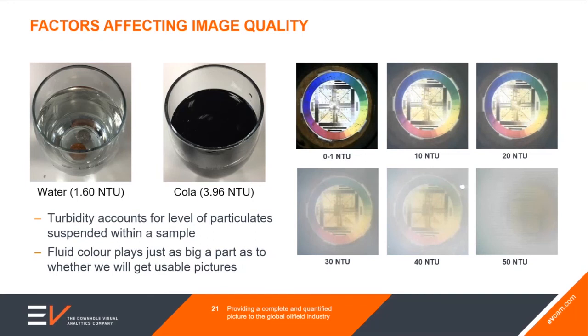We have very experienced operational engineers and a planning team who will go through different scenarios and mitigations that we can either circulate with a clean fluid, we could bullhead a static column to get it to the right depths and area of interest, or we can actually produce the well and ensure that we have clean produced gas or clean produced water over the area of interest. So we'll work up those scenarios, and when we get to the well, we'll try and execute them in that way, that if we don't get success first time out, then we'll learn what was the issue and we'll apply a different strategy to try and get it done.